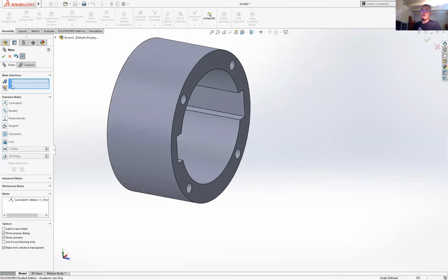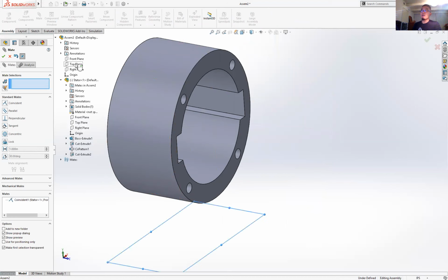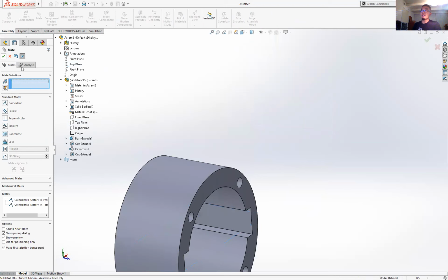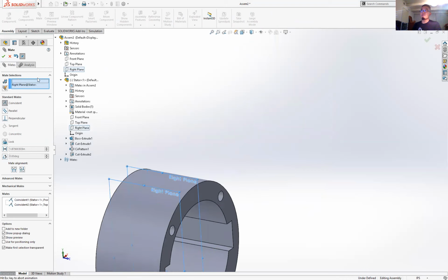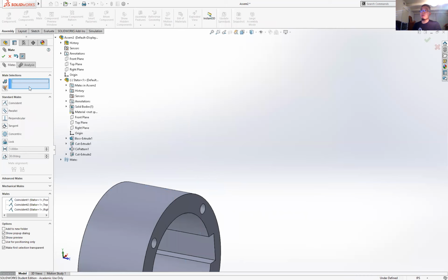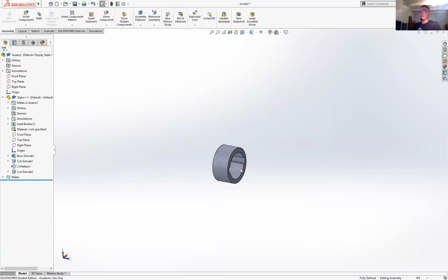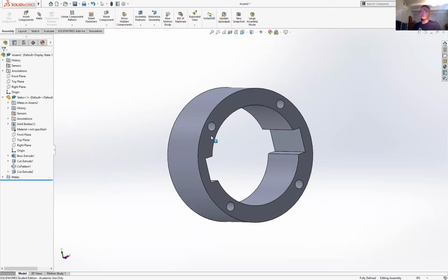Now, while I have this mate tab up, look at how I have another design tree. I can now go top and top, bang, okay? And I check. And so here I still have that mate design panel up, right and right, bang. Okay, and they ask me, do you want any more? And I go, okay, I'm done. Okay, very good. So I scroll in and out, and now everything is locked.